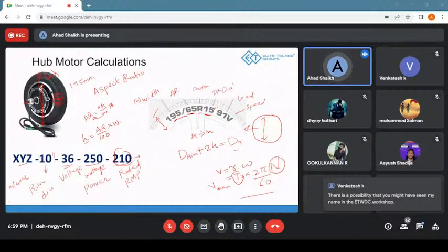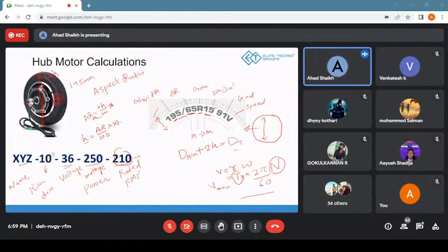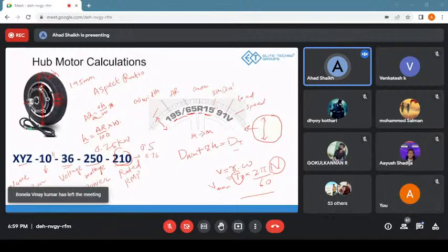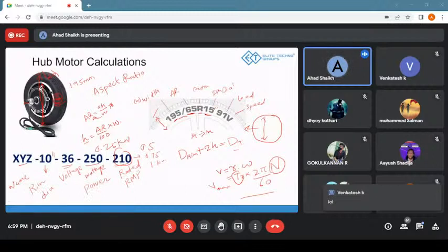So that's how you can calculate the maximum speed that you can achieve by installing a particular specification of hub motor. There are multiple specifications available. This is a very low category vehicle, so it's around 0.25 kilowatt of motor, but there are 0.5 and 0.75, then 1 kilowatt BLDC hub motors that you can use. But RPM is limited here.